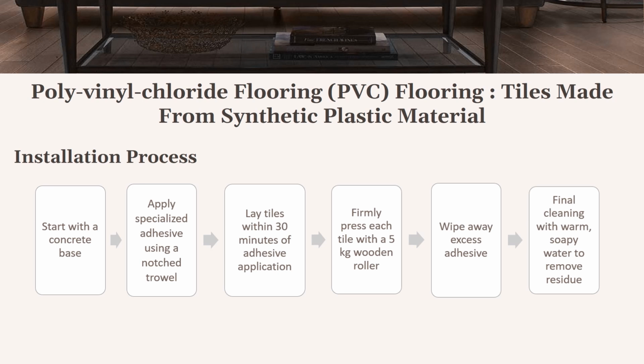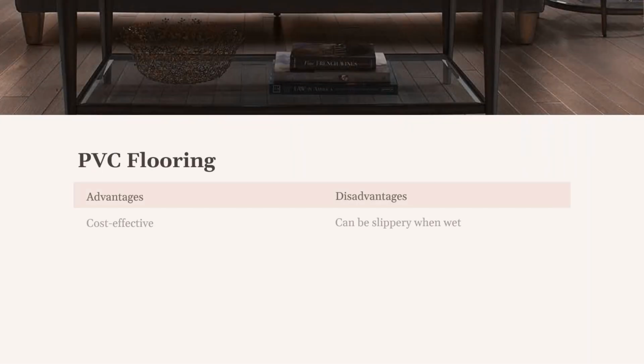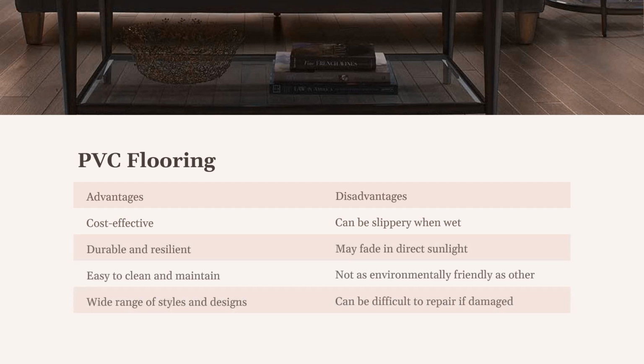Once in place, each tile is firmly pressed using a 5 kg wooden roller to ensure proper adhesion. Excess adhesive is carefully wiped away before the floor undergoes a final cleaning with warm soapy water to remove any residue. This process results in a resilient and pleasing flooring option. PVC flooring offers several advantages, including durability and ease of maintenance. Its smooth surface is both attractive and practical, facilitating straightforward cleaning procedures.